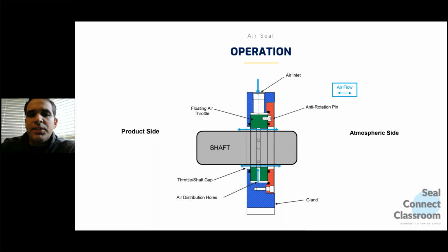That back pressure creates a barrier inside the seal that, as long as the pressure delivered to the seal is higher than the head pressure at the sealing location, which is typically low in the food industry because most mixers, blenders, and conches are basically open, not pressurized vessels, will form that barrier and hold back whatever product is inside that application. We discussed chocolate, but this also works on dry powders as well, and any other foods you can think of. It'll just keep it inside the application.